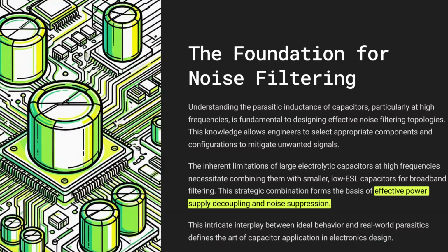And if we tie this all back to oscillators, the theory that governs all of it is the Barkhausen criteria. For an oscillator to sustain itself, the amplifier's gain has to be enough to overcome all the losses in the feedback loop. The overall loop gain has to be 1 or slightly more. That's how filters become clocks.